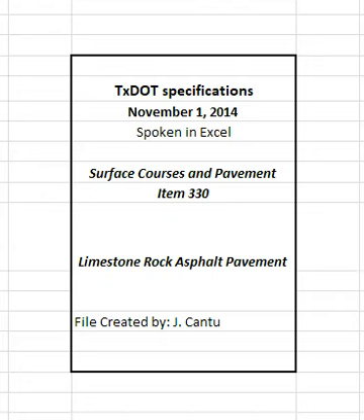Avoid displacement of the mixture. Correct any displacement that may occur to the satisfaction of the engineer. Ensure pavement is fully compacted before allowing rollers to stand on the pavement.